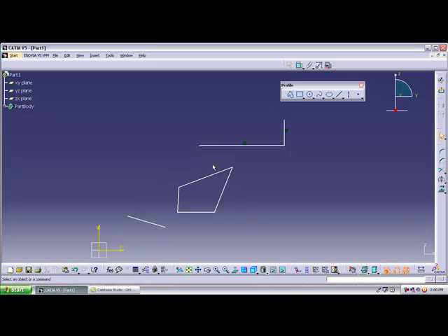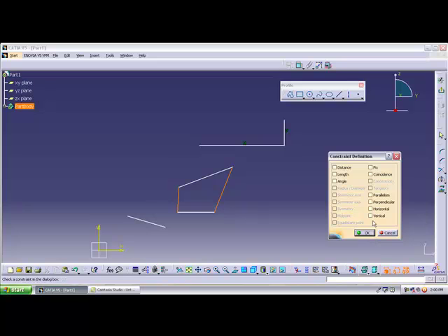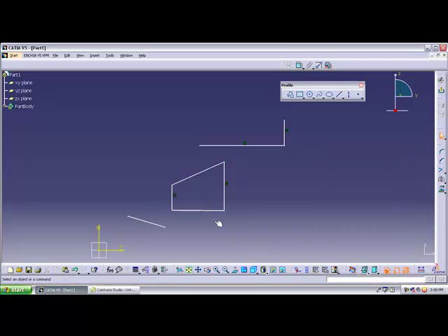Like this, I also want to make the rectangle an exact rectangle, meaning two opposite lines, these two lines are vertical, these two lines are horizontal. Okay, select these two lines and select this object. Here what constraints can you apply? Here you get vertical. I want to apply a single property to the two lines. So these two lines are vertical.